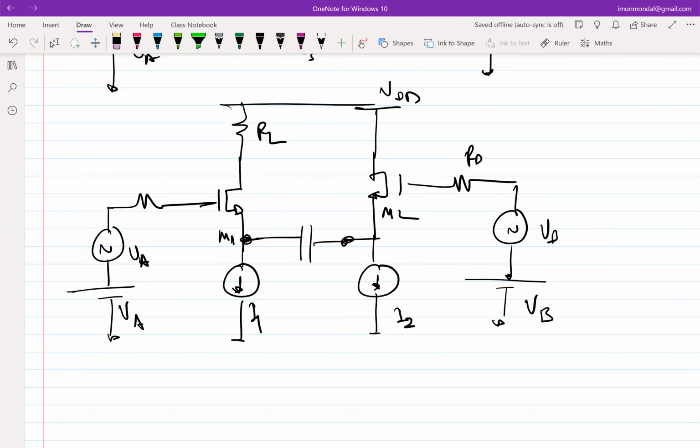So now this will work definitely. But in most cases, M1 and M2 are identical, because we wanted the differential amplifier to be symmetric for its transfer function from either of its terminals, right? So we wanted M1 and M2 to be identical.